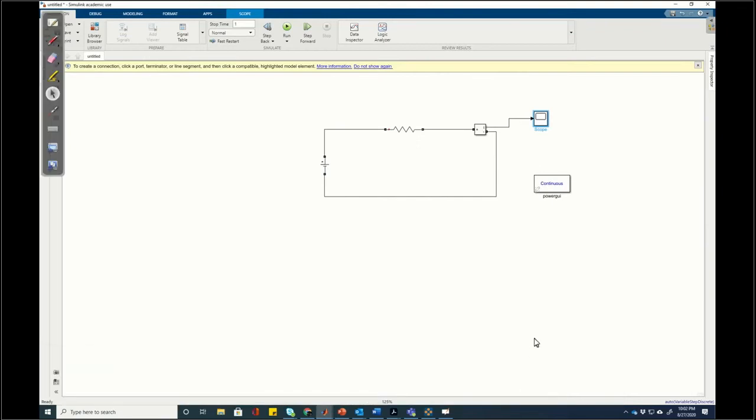the formula, the Ohm's law that we just saw now in the lecture slide. V is equal to I times R. You know that the voltage here is 10 volts. That's what I've chosen here. The resistance is editable. I could have given any value here. So I chose R as 2 ohms, given by this Greek symbol ohms, right? So this is a representation for the units for resistance.